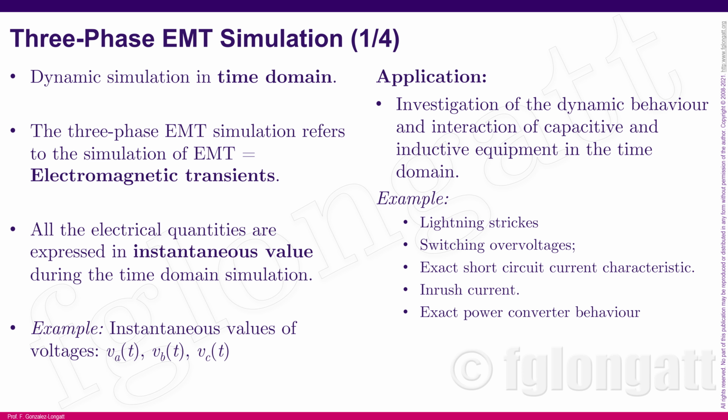okay? For instance, overvoltages created by switching in extra high voltage or ultra high voltage: opening a circuit breaker is a serious situation because you will excite some traveling waves inside the system, okay? It's very important that you take those overvoltages into account when you are working with insulation, okay? Also, when we are using power converters, it's very important that we have the full detail of the short circuit current.